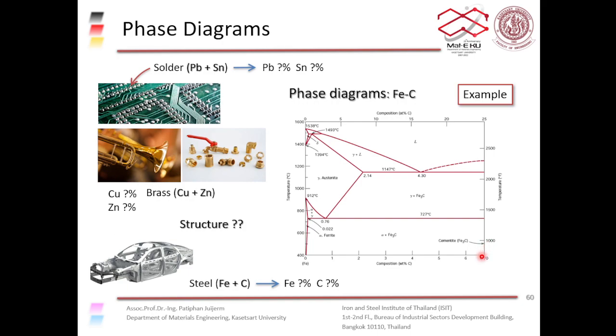But if you are looking at it as an atomic percent up here, the atomic percent of carbon, you can see that because the compound is Fe3C, you have 3 iron atoms and 1 carbon atom. So in total, you have 4 atoms, 1 carbon atom and 3 iron atoms. So the carbon atom is exactly 25 atomic percent, 1 in 4, right? And the other 75%, those are the iron atoms.